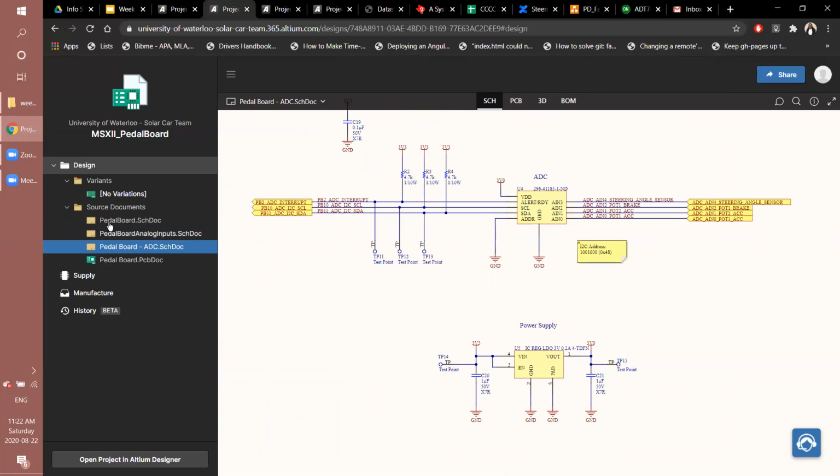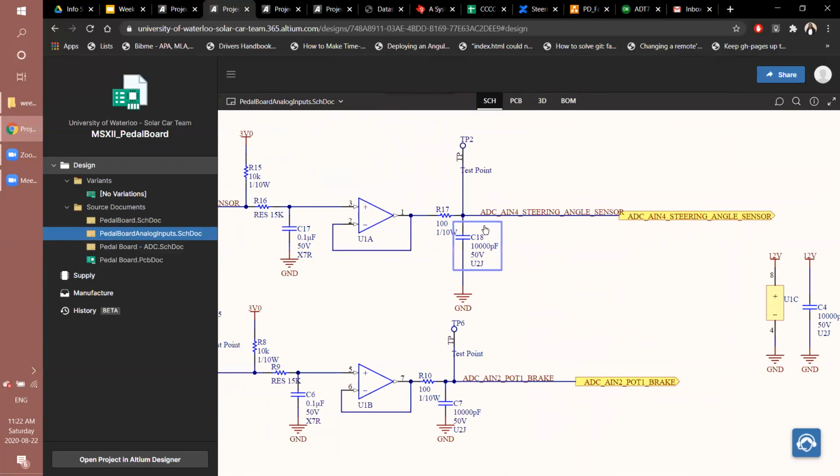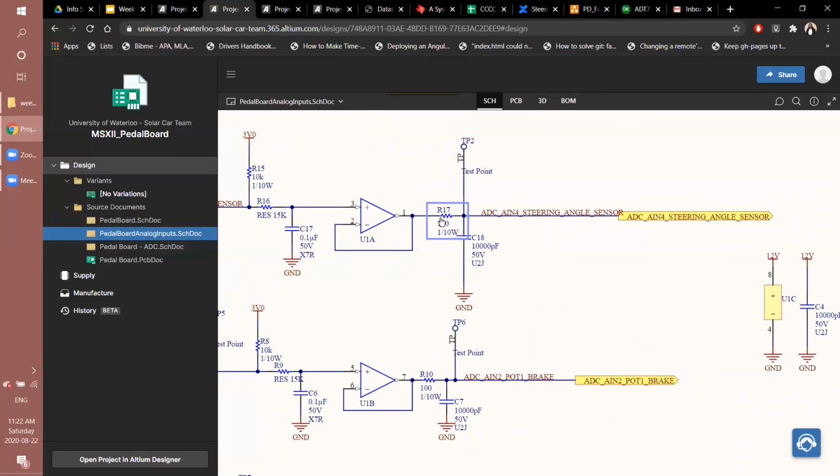And also something to just note, you might see a resistor and capacitor here, and you might think, oh, is that an RC filter? It is not. This resistor is simply for current limiting for the outputs of this buffer. And this is, again, just a decoupling capacitor.